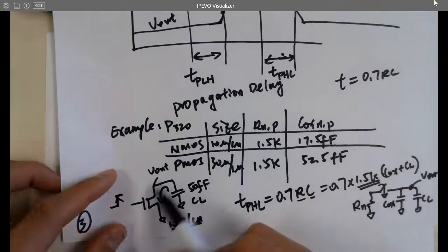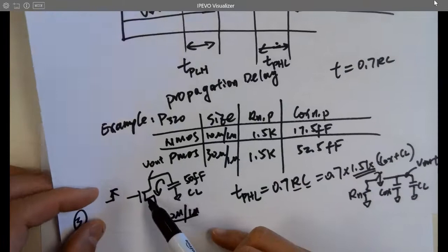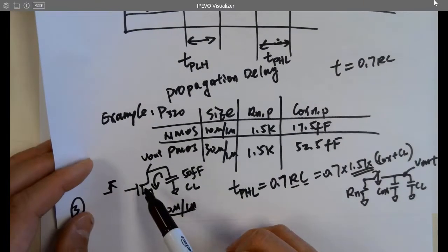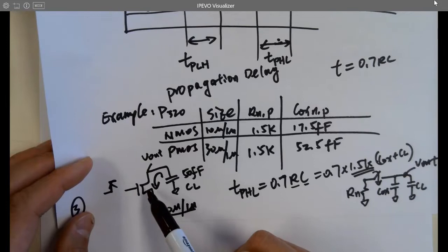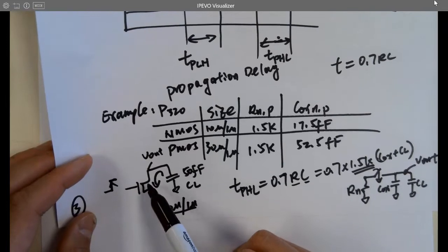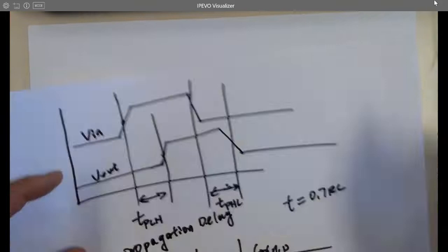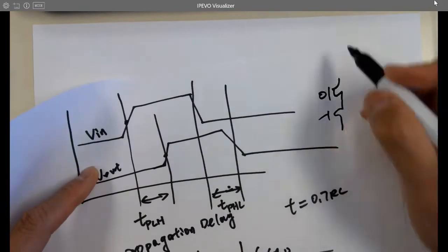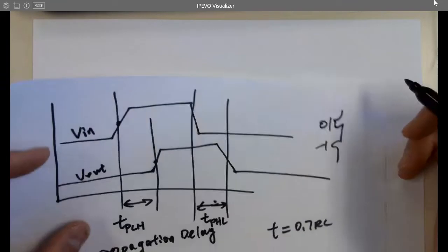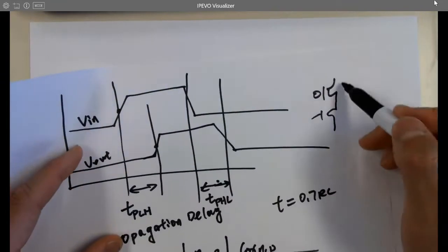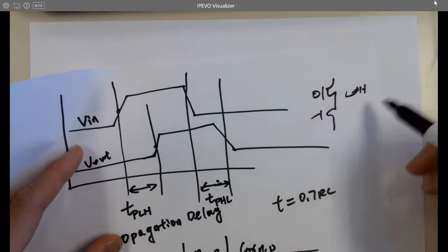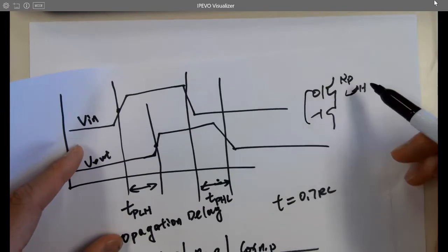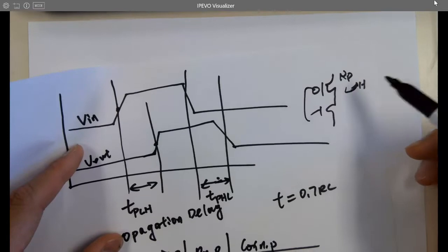The circuit here, right? I guess we don't really care about... We have no signal going in. I see, so usually the low to high happens for the PMOS because PMOS is better at conducting VDD. That's why for CMOS technology, we always design PMOS on the top to do that low to high stuff. So you have to care about the RP and Cox P.